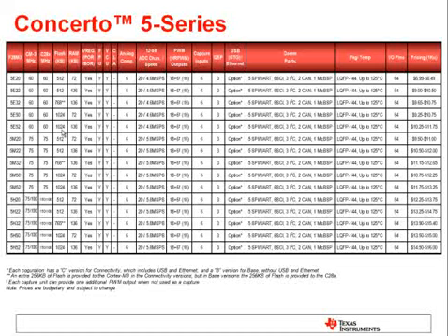Then there's the extra 256 KB that goes to the M3 core on connectivity devices, which are the ones with USB and Ethernet, and it goes to the C2000X core on base devices, the ones without USB and Ethernet. This way, connectivity devices can get more flash for the Ethernet and USB stacks, while the base devices can focus more on the algorithms that are run on the C2000X core. The extra 64 KB of RAM, however, that varies between these devices, are split into masterable blocks, so these are much more flexible.